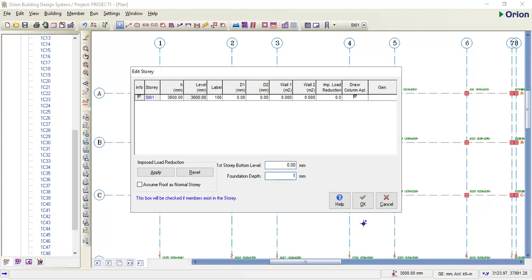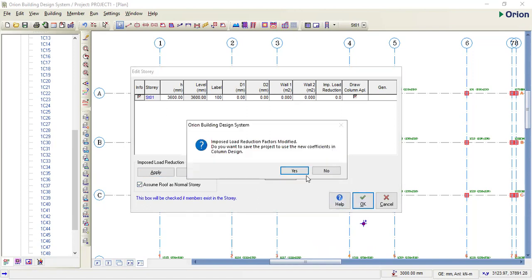We use 1.45, from the blinding to the top. We can as well use 1.5, but 1.45 is fine. That was what we used. We assume roof level as a normal story. You apply. Assuming you have your 3D, it will automatically follow.